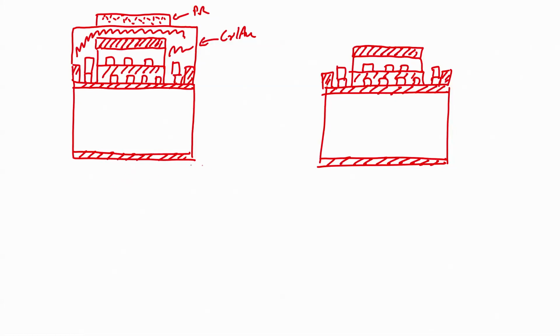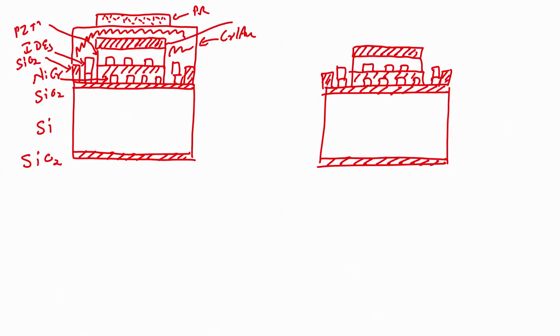And if I write down SiO2, silicon, SiO2, micro heater is nichrome, then SiO2, then interdigital electrodes, then piezoresistive material, then SiO2, right, on which there is a chrome gold, on which there is photoresist.